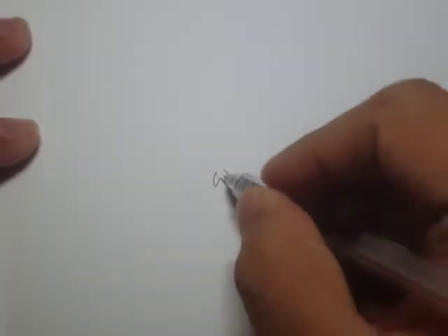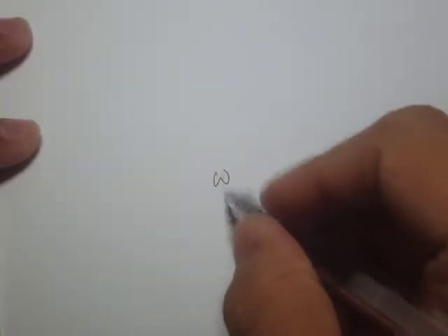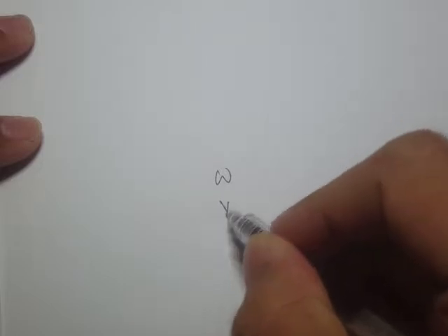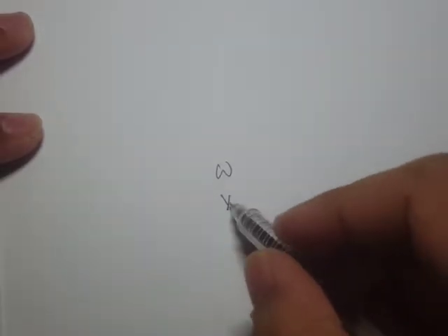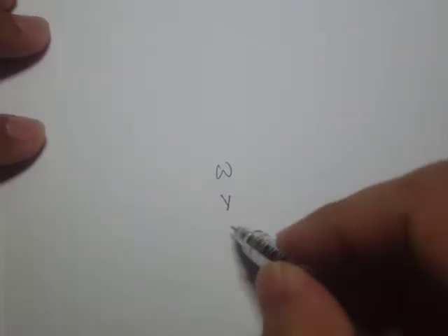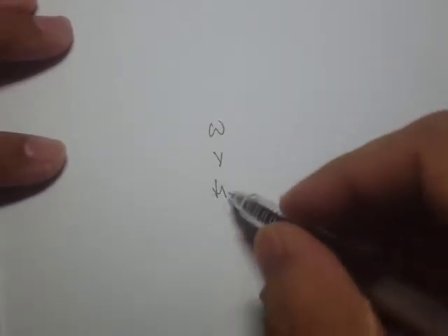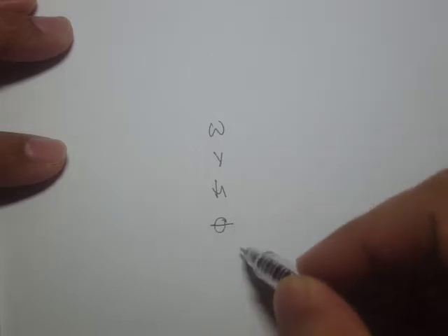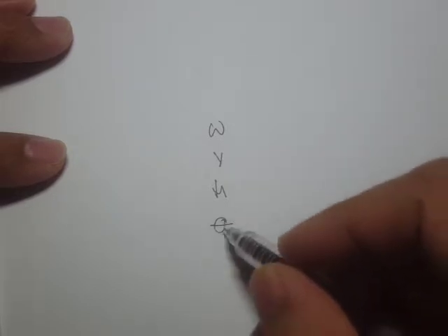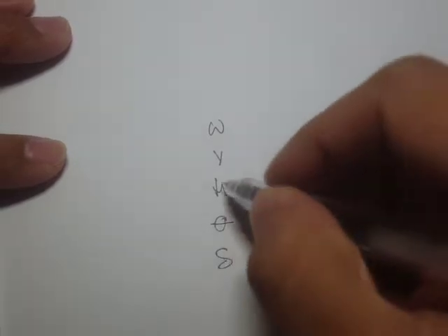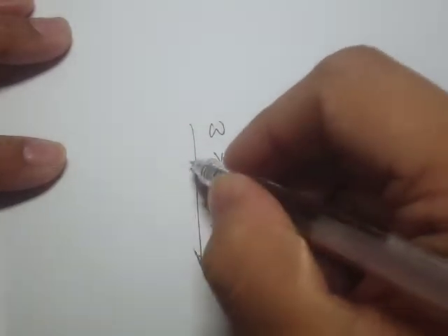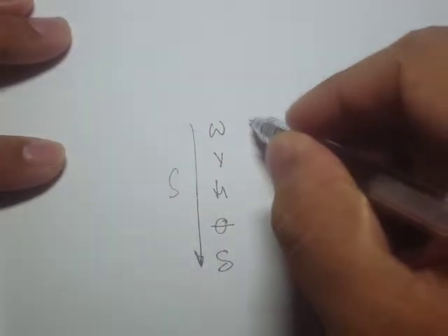So recall that we have this relationship that if you integrate the load, what you get is the shear, right? And if you integrate the shear, what you get is the moment. And if you integrate the moment, what you get is the slope. And then after that, if you still integrate this, then what you get is the deflection. Okay, so recall this relationship.